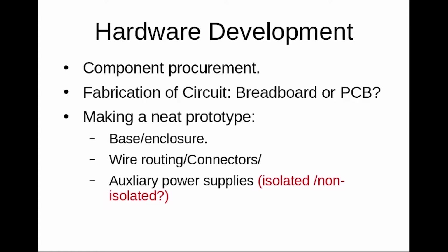This is true for higher power handling converters also. If the signals being handled are of low frequencies, typically 1 to 10 kilohertz, and if the power level is not that much, breadboards should be fine. Otherwise, you may have to go for a proper PCB.